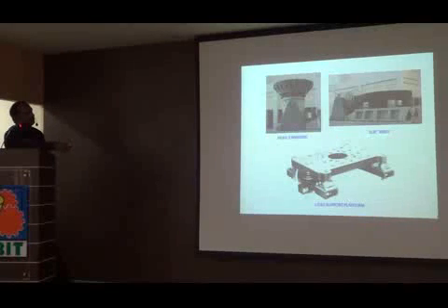For example, I have some missiles which are 2 meters or 3 meters in diameter. So how do I test them? I may have a shaker of 500 mm or 600 mm. Then I need some kind of head expander, meaning expanding the head, so that at the top you have 3 meters and at the bottom you have 2 meters. But this should have a frequency range so that I can operate my system up to 2000 Hz. So this fixture should be designed for 2000.